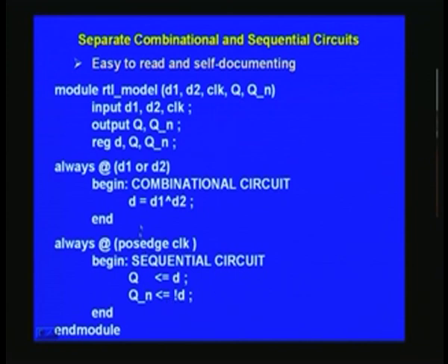So, coming back to this, we have not said what a register is. You notice that the outputs in this always block are d, q and q underscore n. So these are all registered values. That means it is basically a flip flop here. It is not really a flip flop in the usual sense of a sequential circuit, but still it memorizes that event, because whenever there is a change, only then we take action.